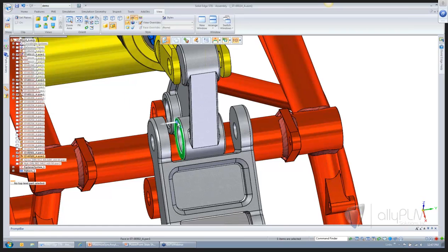So what I want to do here is select this face, and before I make my edit, I want to transition, or translate, I guess I should say, the origin of my steering wheel. So by holding the Shift key, I'm actually able to move the origin point of my steering wheel. And I'm going to enter 3 millimeters in here and enter that. So now the origin of my steering wheel is offset from the face by 3 millimeters.